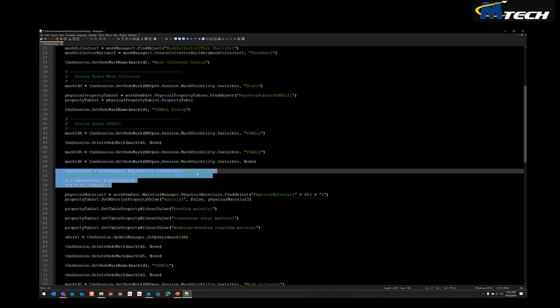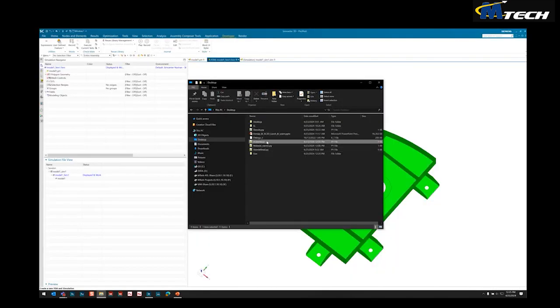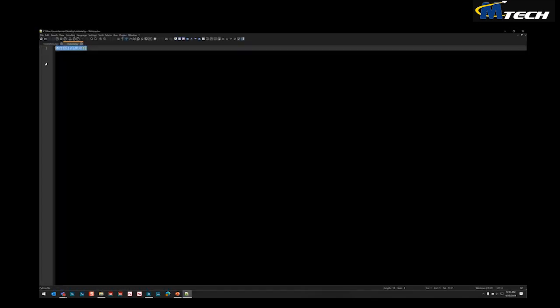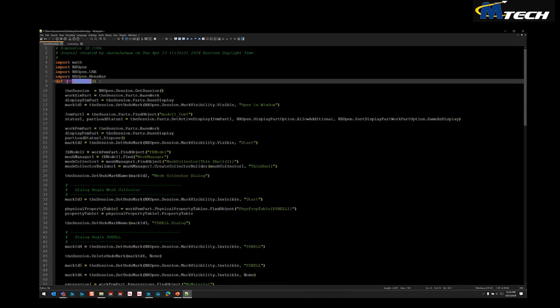So we're just going to assign the material. So these 5 lines right here are all that's needed to be changed other than what was automatically created. Okay, and I can help set that up for a particular project, but we're just setting variables equal to each other. Okay, and then the other file that's required by HEEDS is simply to call out that function that we defined here at the top.